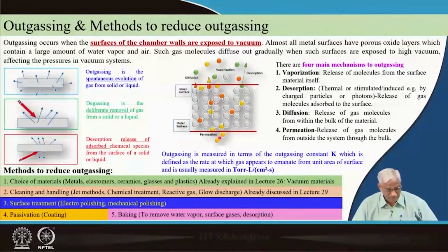That is permeation. These molecules are coming all the way through the body. This is the body thickness of the shell, the chamber shell. I am zooming in here. So, some gas molecules may permeate through this and come out. There may be some molecules within the body in the formation of the stainless steel, and they will come out of it, that is called diffusion.